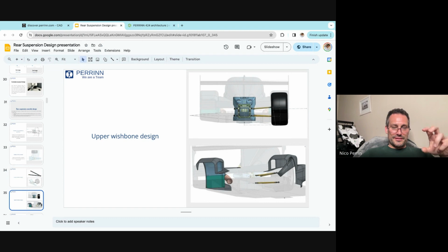There's a lot of work in terms of packaging with the wishbones. Typically at the rear, the wishbones are quite close together, but that creates fairly high load on the suspension legs. This is all to do with the aerodynamics. So there is a compromise between the diffuser volume and the top body, but still allowing enough space for the suspension to be stiff enough.